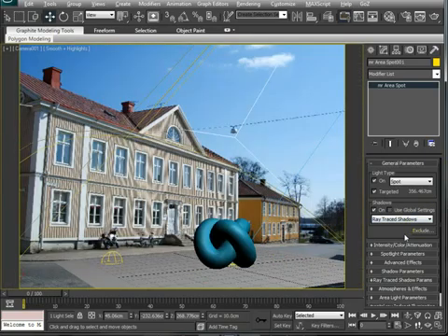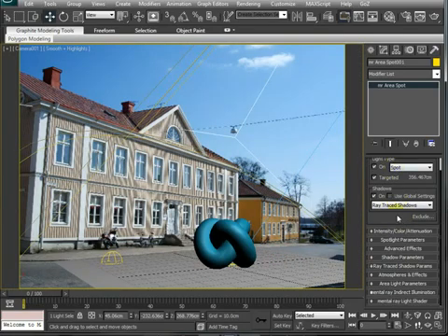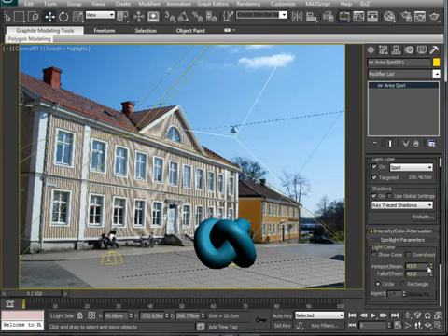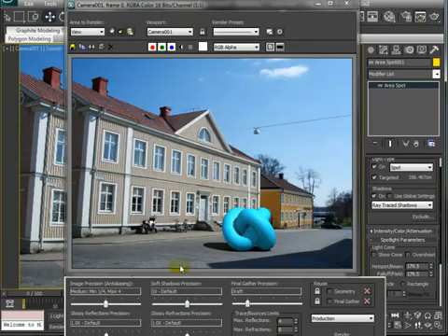we can change some of the settings for the light. The first thing we're going to change is in the spotlight parameters. I'm just going to push this hotspot beam angle right up to 179.5. If I then re-render, you can see that we've introduced these hard shadows into the scene now. So these are matching the shadows here from this motorbike and coming from this building to match the scene up to what we had in the source footage. So that's a good start, but you'll note that the shadow is very, very harsh, as in it's got a very defined edge, and it's very, very black.